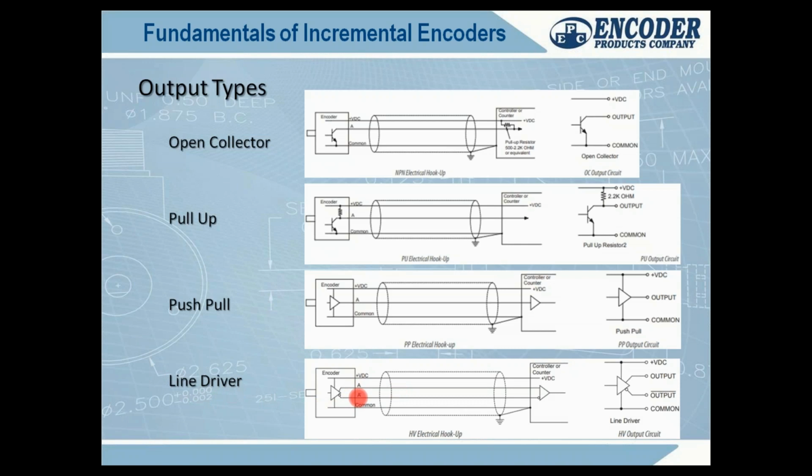If you're an OEM, you're designing it in, you don't need the complements. Why have a wire that could get mishooked up and cause you problems? Order the push-pull. I encourage OEMs that really don't need complements to go with the push-pull. But on the end user side, you're not sure what you need, you don't have to wire them up for it to work. Just make sure you don't short out those complements. They're there if you need them.